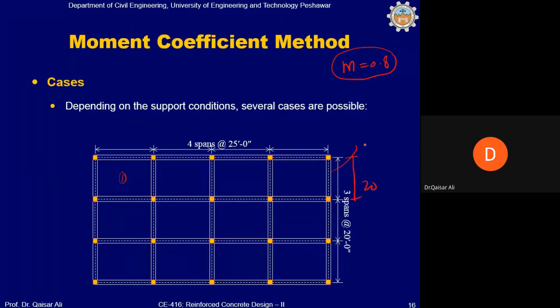and if the beam width is 12 by 18 inch, so width is 12 inch, तो हमने कैलकुलेट किया था LA was equal to 20 minus 1 feet, so 19 feet. Okay, and LB was equal to 25 feet center to center length minus support width which is 1 feet, 24 feet. ये भी जरा नोट करें, सही। Clear length of shorter direction is 19 feet and clear length of longer direction is 24 feet.